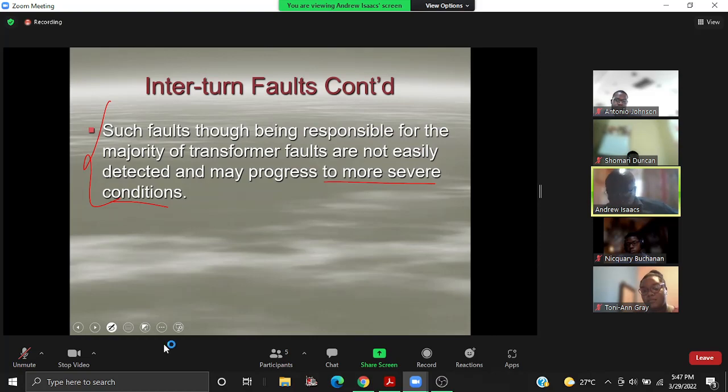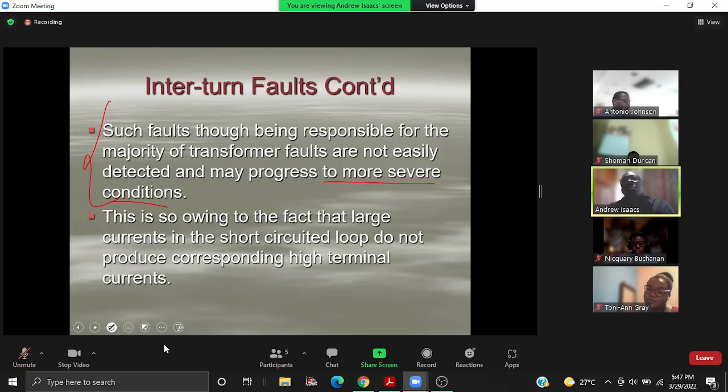So it's not just looking at these pretty screens, and you see something like PowerWorld and it looks all nice and fancy. All right? You have to be able to determine when the abnormalities are coming in by way of alarms. Right? Because it's best to manage the start of these faults than to allow them to escalate so that you are forced to remove the transformer. It's best to go and do your switching, take out the transformer, have it repaired or whatever you want to do with it, and then restore it to proper operation.